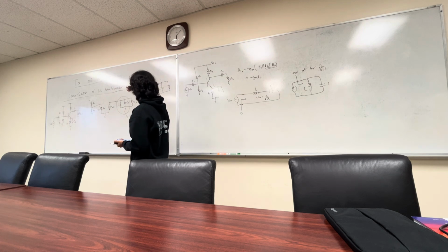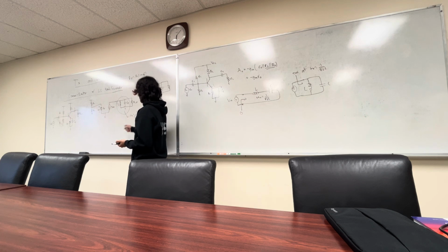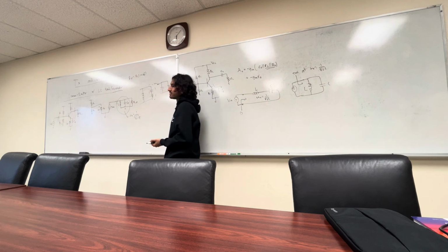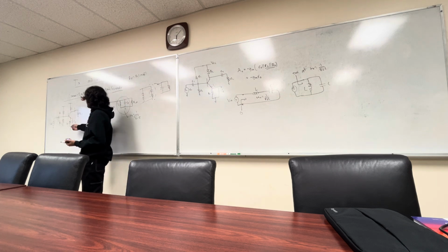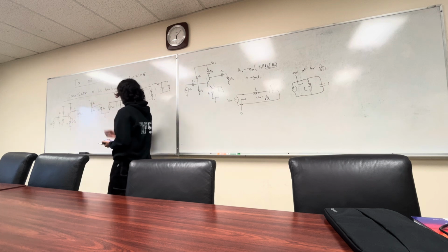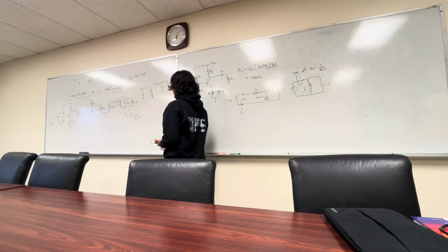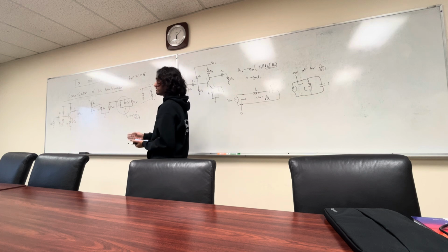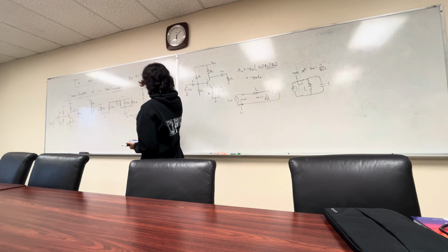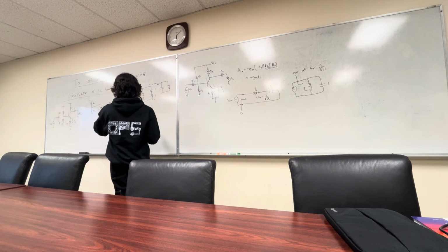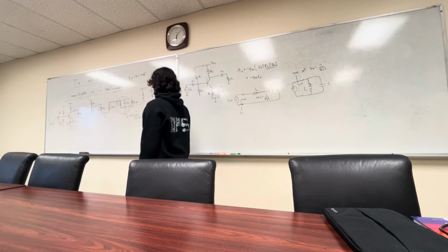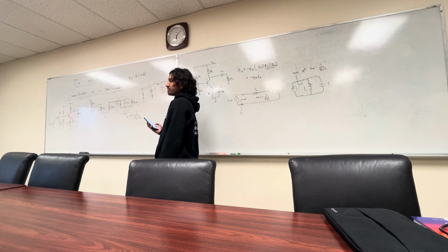So if we make an amplifier at 1 megahertz, we make sure that omega naught is 1 megahertz times 2 pi, and figure out what L and C values we need. If we want it at 5 megahertz, again, do the same approach. So you'll see it's kind of the same idea here as designing the CE value, right? Make that certain value such that at that frequency, that impedance is 10 times less than RE, at which point most of your signal will steer towards CE. Kind of the same concept here. Again, it's a frequency dependent derivation of the values. So that's the important part.